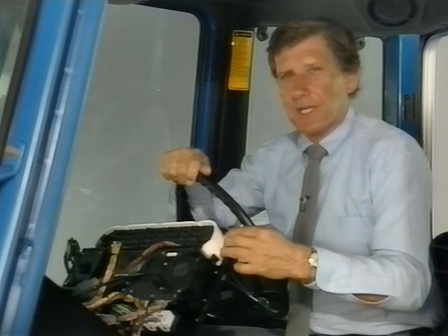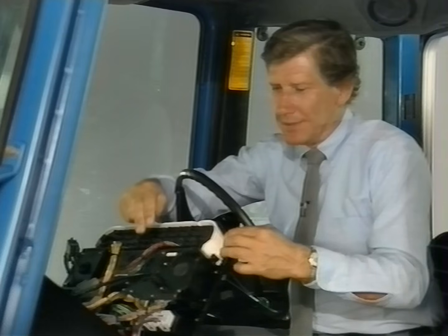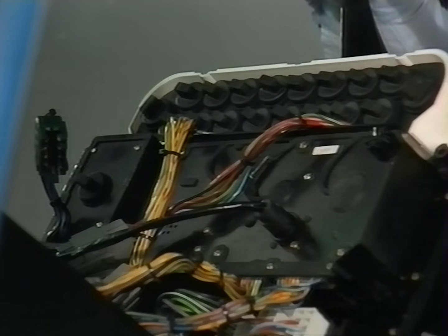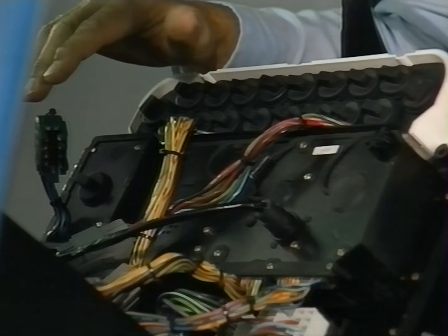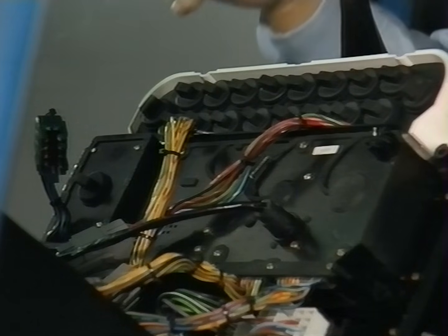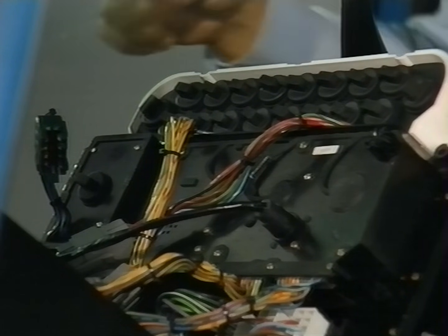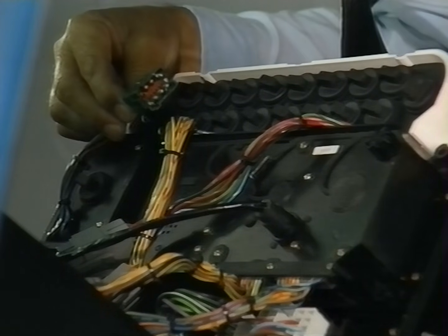The wires from the radar speed sensor plug directly into the back of the electronic instrument panel, while those for the implement status switch and axle speed sender are routed to the tractor wiring harnesses. The wires then run to the rear main harness. The tractor performance monitor plugs into the rear main harness by means of an 8-pin connector.